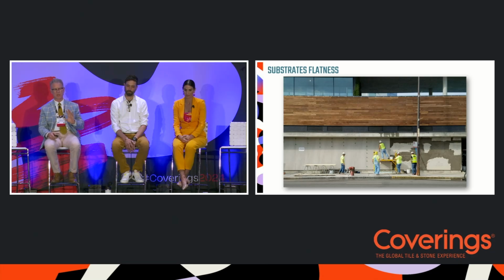I have this slide in this section to show you all that patching material that is filling in the low areas of the backer board so that very large gauged porcelain tile panels will have a flat substrate to stick to. I'm just going to go off on a slight tangent because we do have some time. You see the patching. You understand we're filling in the low areas to make that substrate flat. And by the way, this is a crew of tile setters. These are not some special trade that comes in to fix the substrate. Remediating the substrate is one of the many, many tasks that tile setters do aside from actually laying the tile.